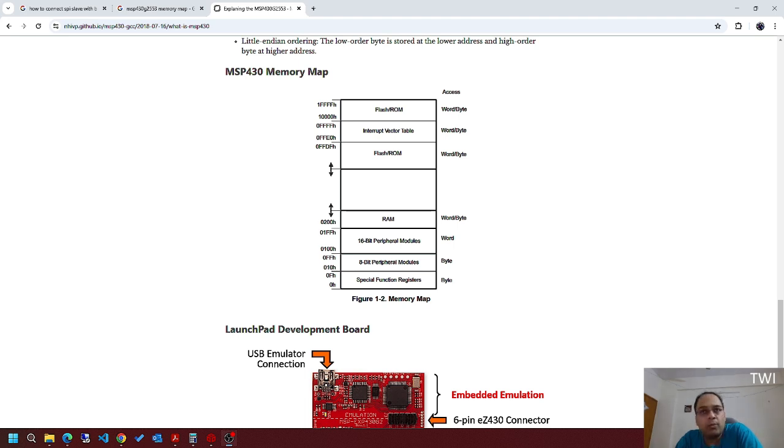One option is to invoke the bootloader using some kind of pin or button. Usually the bootloader can be invoked using a button on your device. You can check the hardware schematic diagram, which will help you identify how to invoke the bootloader using push buttons.